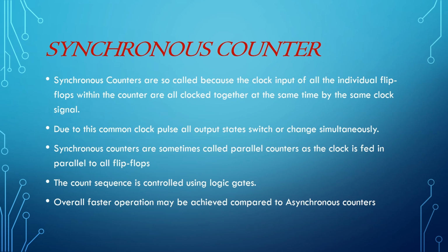Synchronous counters are so called because the clock input of all the individual flip flops within the counter are all clocked together at the same time by the same clock signal. Due to this common clock pulse, all output states switch or change simultaneously. Simultaneously means at the same time.